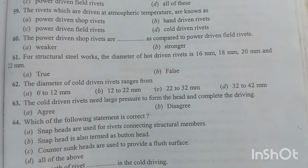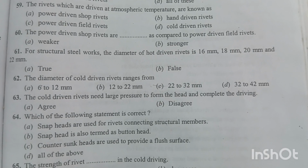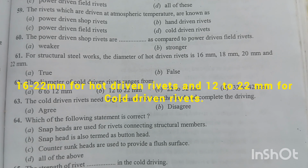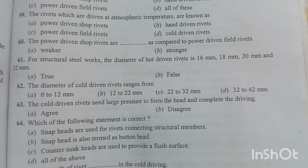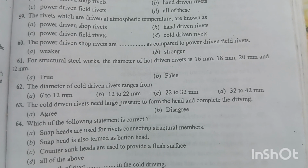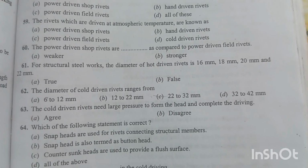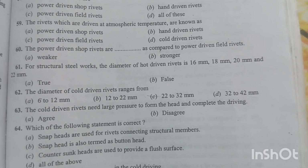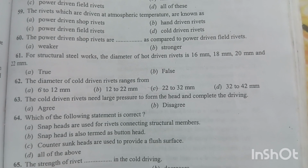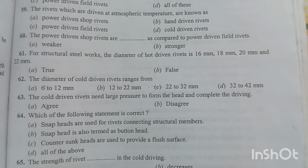Question number 61. For structural steel works, the diameter of hot driven rivet is 16 mm, 18 mm, 20 mm, and 22 mm. Option A is the right answer, true. Question number 62. The diameter of cold driven rivets ranges from 12 to 22 mm. Option B is the right answer. Question number 63. The cold driven rivets need large pressure to form the head and complete driving. Option A is the right answer, agree.